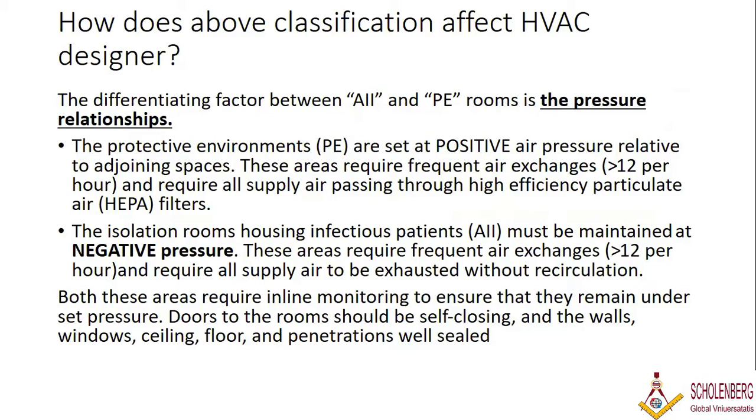Now, how does this classification affect us as air conditioning design engineers? The differentiating factor between these two rooms is the pressure relationship. The protective environment, the PE rooms, are set at positive air pressure relative to the adjoining space. You have to have the relation.